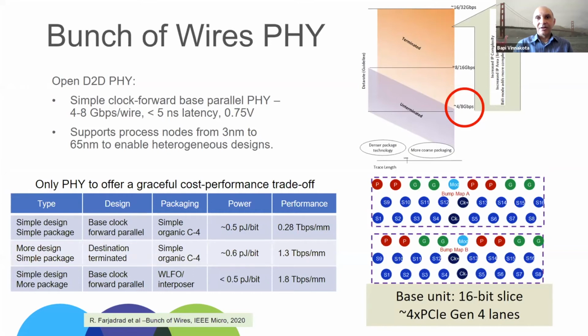Remember how I said a PHY can either be a wide parallel bus, which goes off the die, or it can be a SerDes bus, which is more like an off-package bus. As you know, this is our attempt at having the cake and eating it too, basically. We're trying to make a PHY which works with multiple packaging technologies and is easy to design.